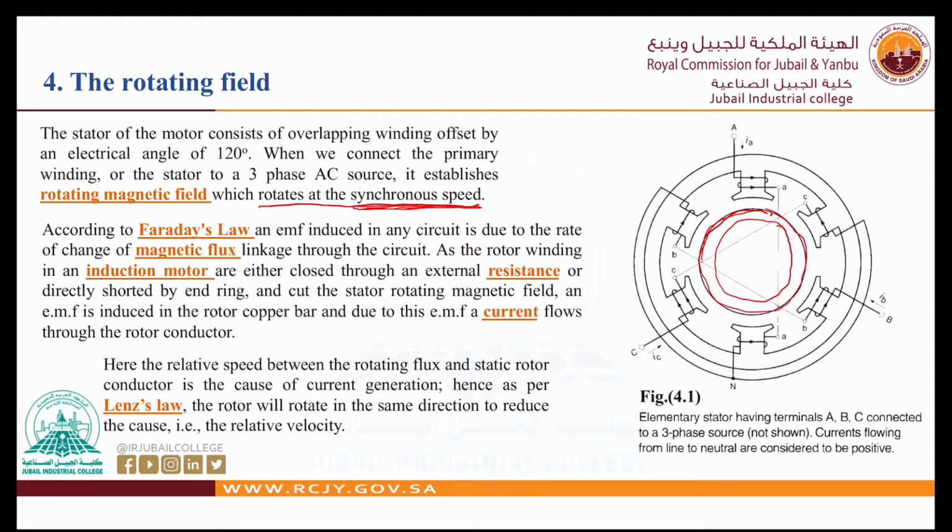Okay, and as you know, this is the air gap. The rotor will not touch the stator, right? We will have a small air gap in order to move the rotor. So if we have a rotating magnetic field in the stator, either clockwise or anti-clockwise, then this rotating magnetic field will go to the rotor, and the rotor is short circuited, so we have a closed circuit.